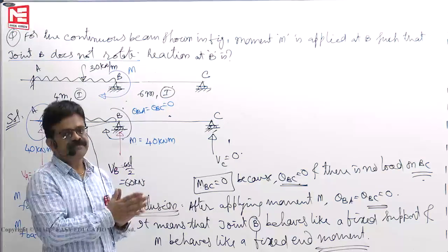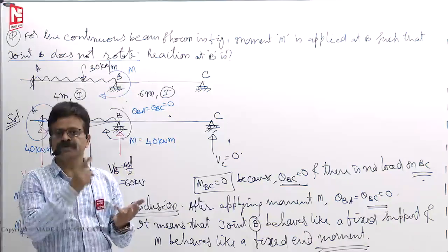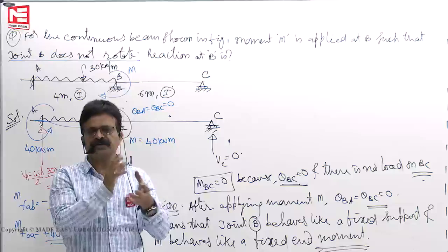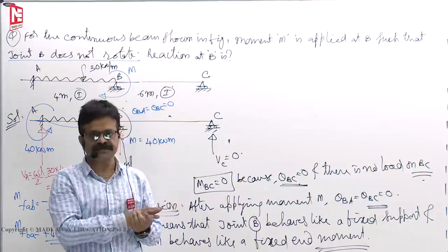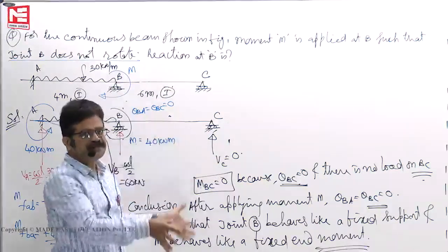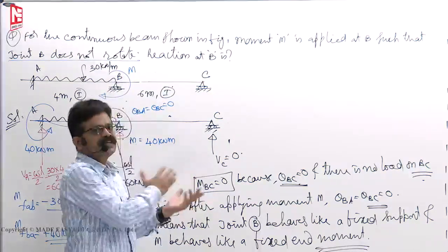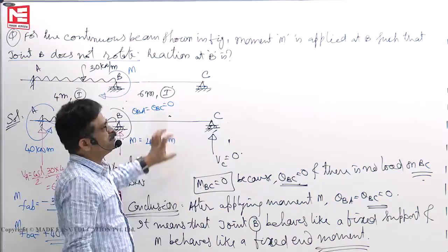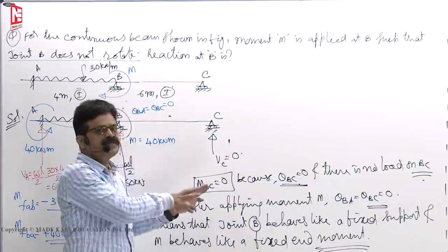In such cases, in statically indeterminate structures, sinking of support, temperature changes, yielding of support, or lack of fit produce some additional reactions in the structure. So if we know how the frames behave due to sinking of supports, then those sinking effects also we can incorporate in the design. What reactions, what fixed end moments, etc., will develop in the frames due to sinking of supports, we will see.